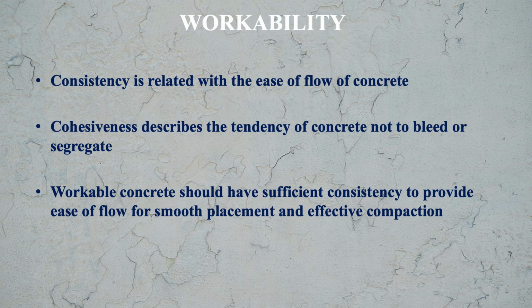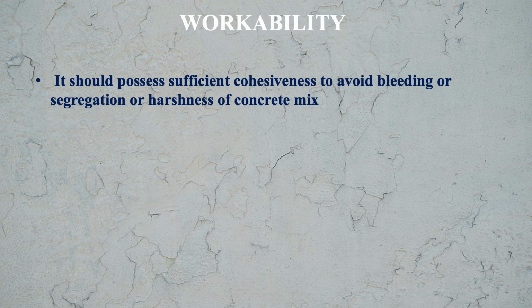That is cohesiveness. Now, workable concrete should have sufficient consistency to provide ease of flow for smooth placement and effective compaction. And it should possess sufficient cohesiveness to avoid bleeding, segregation or harshness of the concrete mix. So these are the two important components, consistency and cohesiveness.